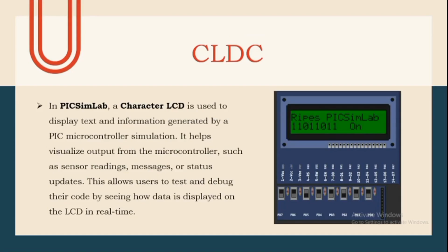And the next component was CLCD. We used a 16x4 CLCD in PICSIMLAB. The LCD displays messages like washing started, rinsing, or completed. It gives visual feedback to the user and makes the system more interactive. It was connected to port D of the PIC.